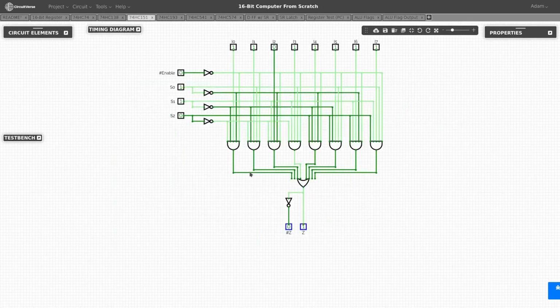Then I started looking to see what it would take to implement the 74HC151 IC. And it takes 3 inputs plus an enable, so I was going to use these 4 signals to handle half the outputs and then duplicate this for the other half of the outputs so that I was able to handle all of the different 16 states that were required in order to determine whether or not a particular instruction is executable or not. And I started thinking about how I was going to be able to do that and the timings required for that.